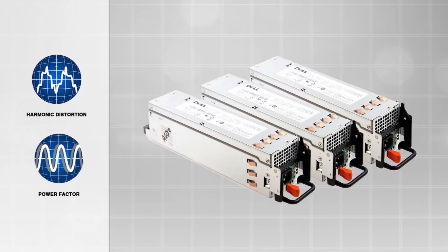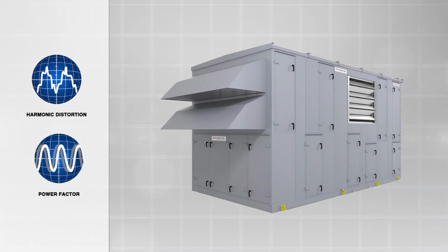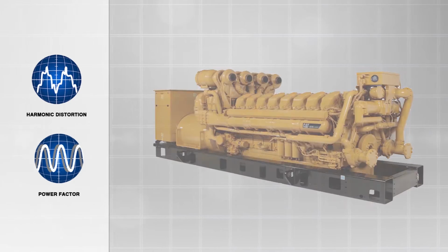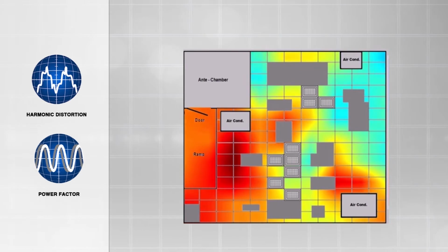The source of harmonics in data centers are from loads operating in the electrical network drawing power in a non-linear way. Power supplies in particular introduce harmonics and add excessive heat into the environment. The sources of poor power factor are typically related to the motors running the HVAC and also from various lighting, transformers, or generators. These distortions are always present in data center electrical environments.